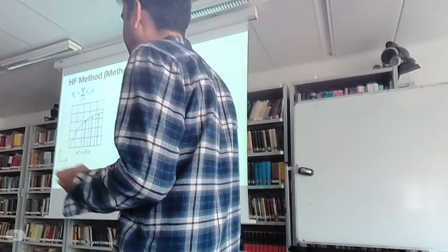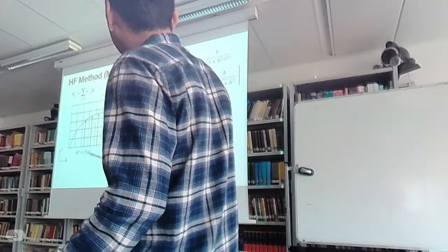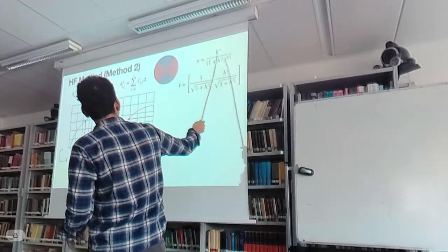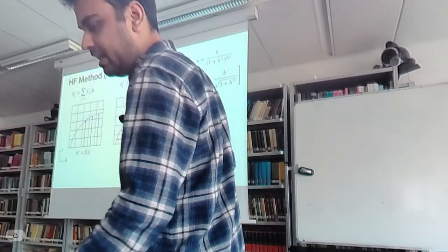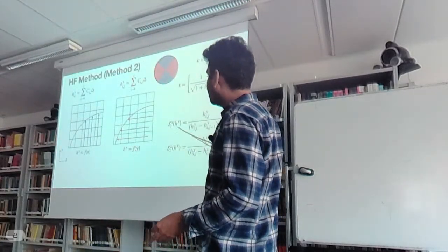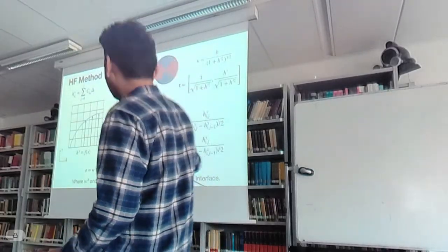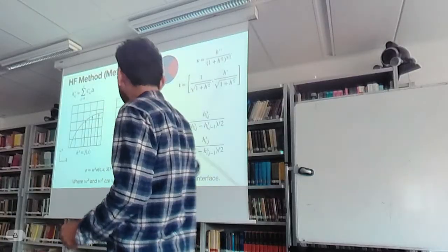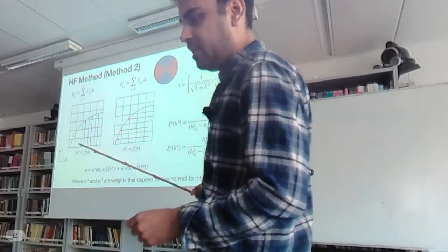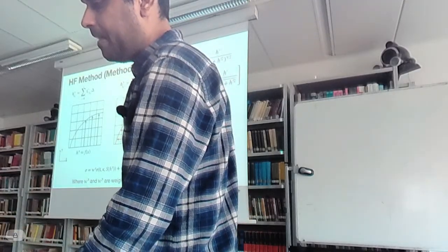So you can have two representations of height functions, and depending on where this interface is oriented, we use either horizontal or vertical height functions to calculate the curvature and the tangent, and we calculate the surface fraction by both approaches, and then we do a weighting of the surface tension tensor with these two weights that are obtained by vertical and horizontal height functions, and we write a surface tension tensor, which of course gives you the surface tension force.